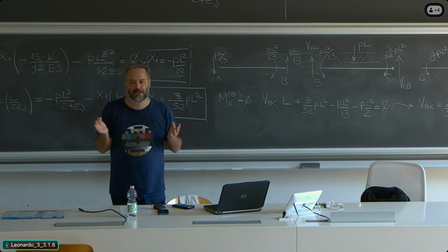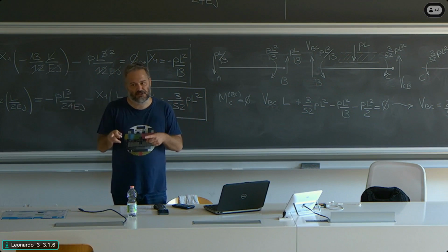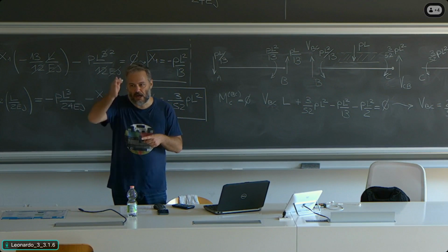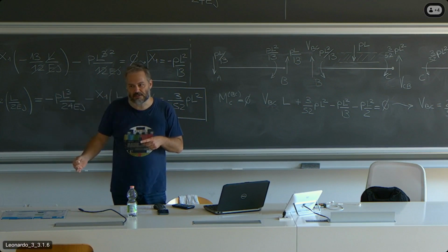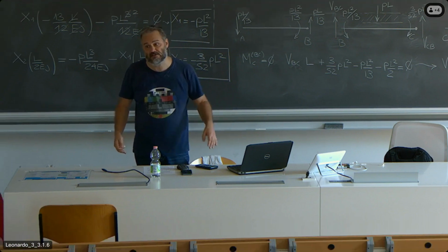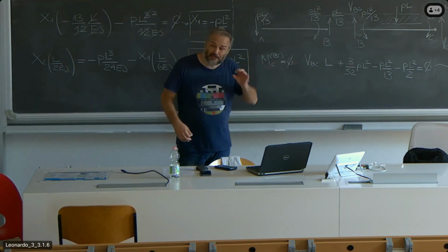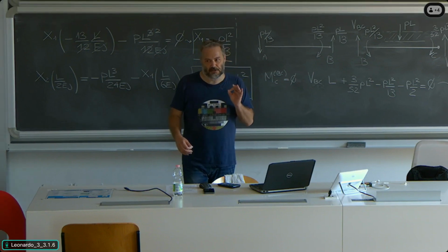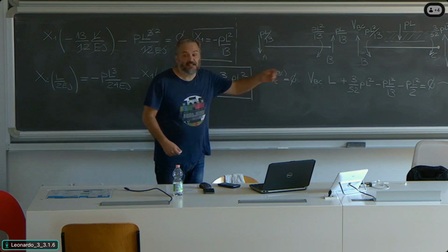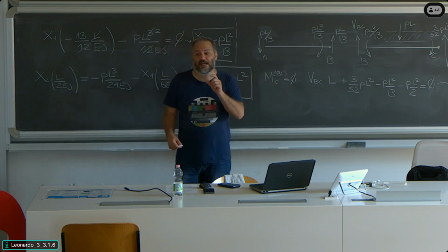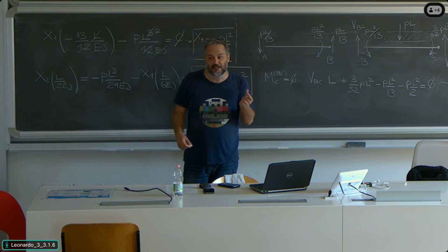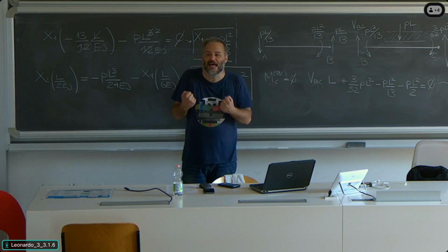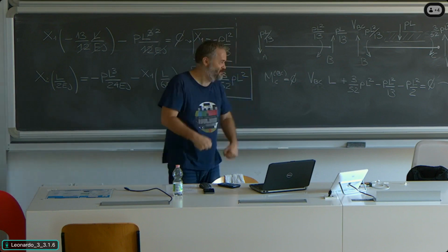If there were no bending moments at the two ends, the load would go, as we saw yesterday, 1/2 on one side, 1/2 on the other side. In this case, as you see, 27/52 is slightly more than half of the load. Slightly more. If there is slightly more load than half of the load at the first end, then we should have at the second end slightly less than half of the load.